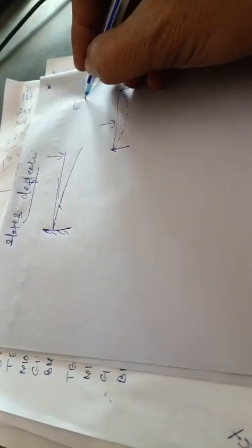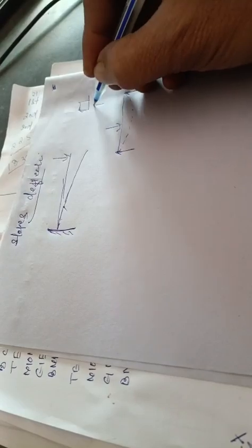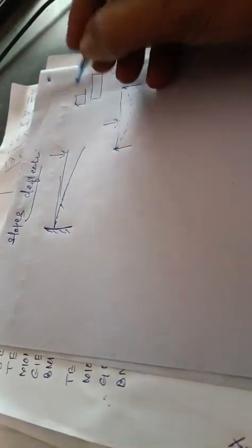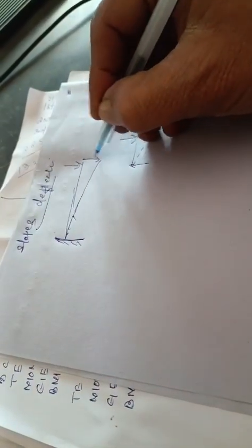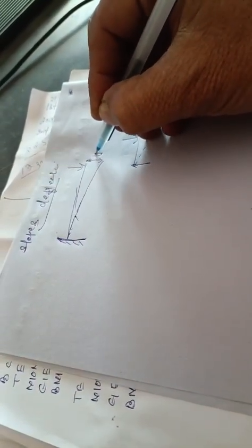The amount of deflection by which the beam deflects depends upon its cross section and the bending moment. If the cross section is square or rectangular, it depends upon the type of material used and the type of section used. This is the deflection amount, let it be y.